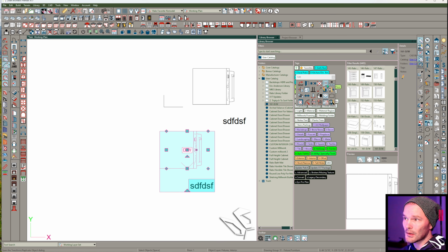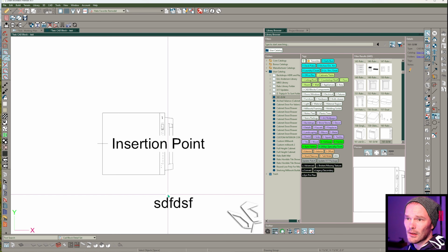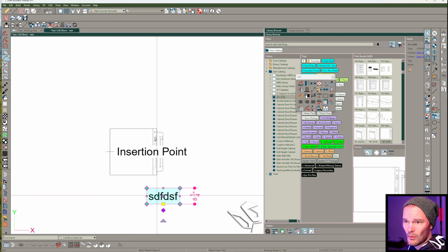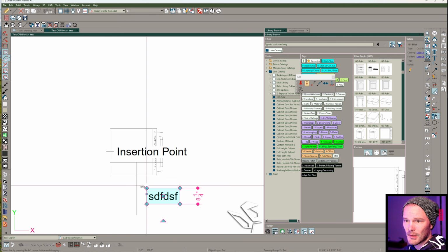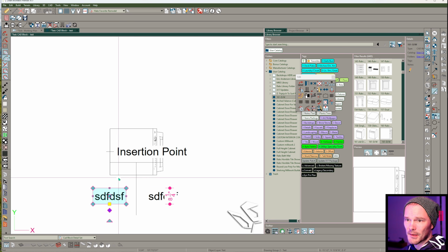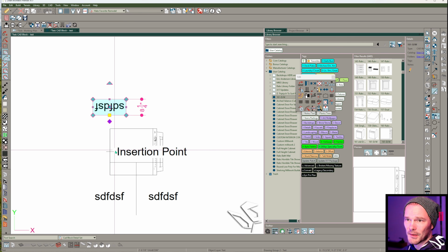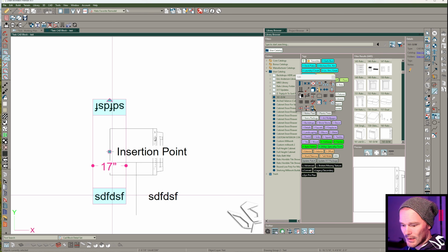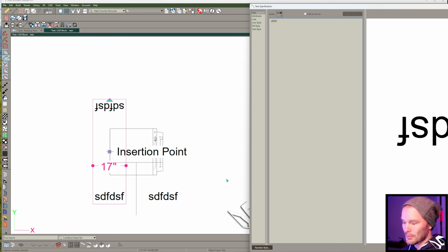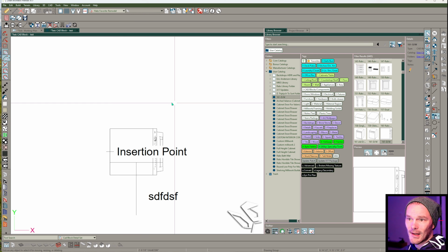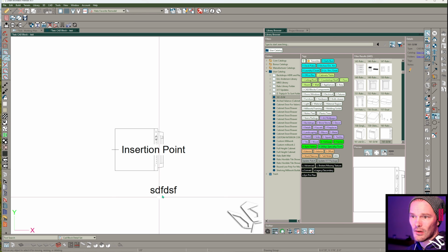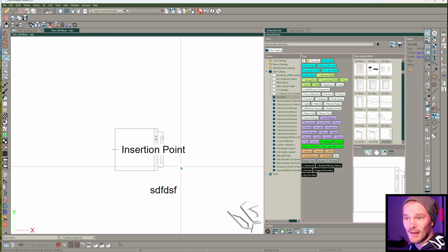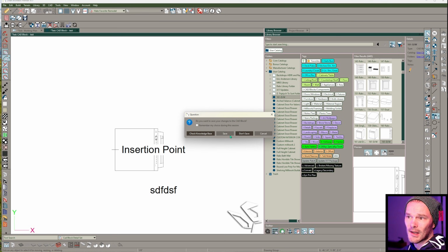So really what you need to do is edit that CAD block again, and notice that I need basically a CAD line from the furthest most face here to be able to understand where the center is, so that I can copy paste, reflect about that center, copy paste, reflect about this center, and now select these two guys, set them to just blank character spaces, and now I've effectively put everything back to center so that hopefully this dishwasher's aligned and that text